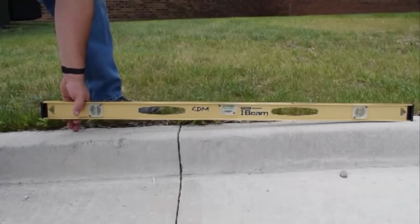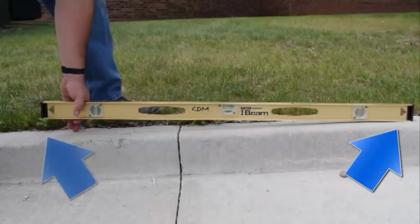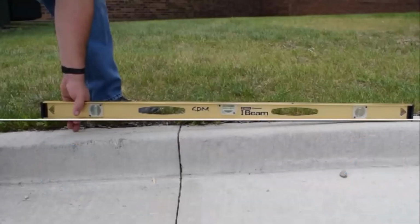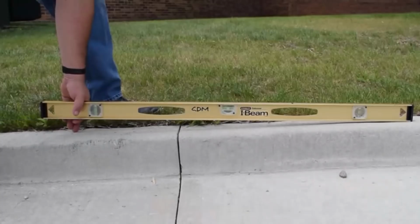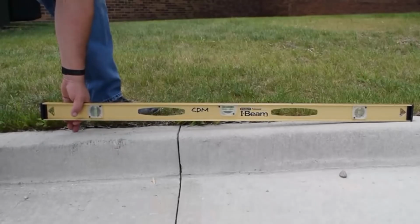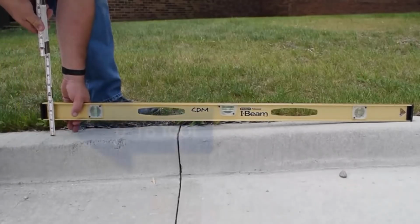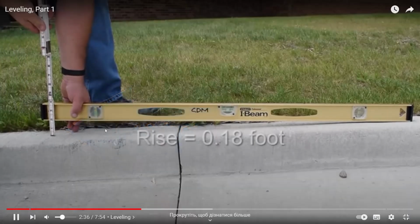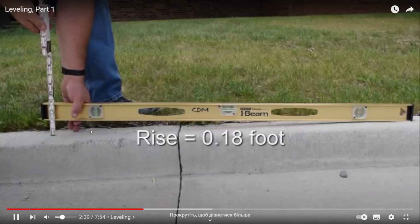Here you can see that the concrete surface at this end is higher than the concrete surface at the other end of the level. The underside of the level is now a line of reference we can use. With the bubble centered within the marks, I can measure down from the underside of the level to the concrete. This measurement is 0.18 feet. Since the other end of the level sits on the concrete, the vertical distance between the two ends is 0.18 feet.